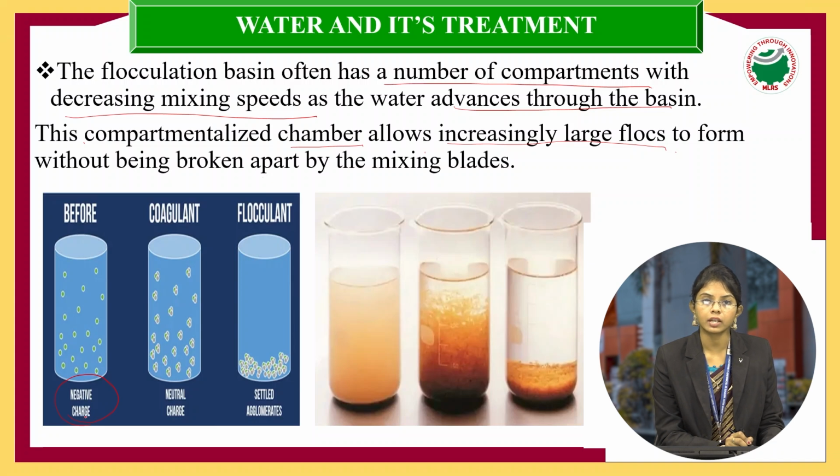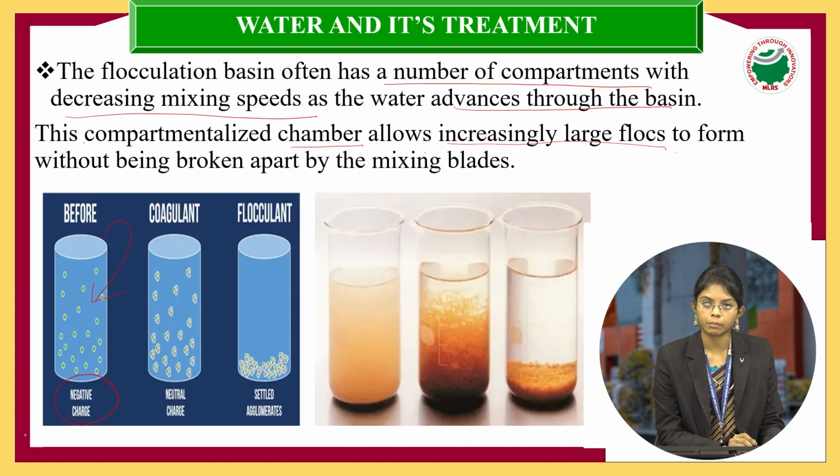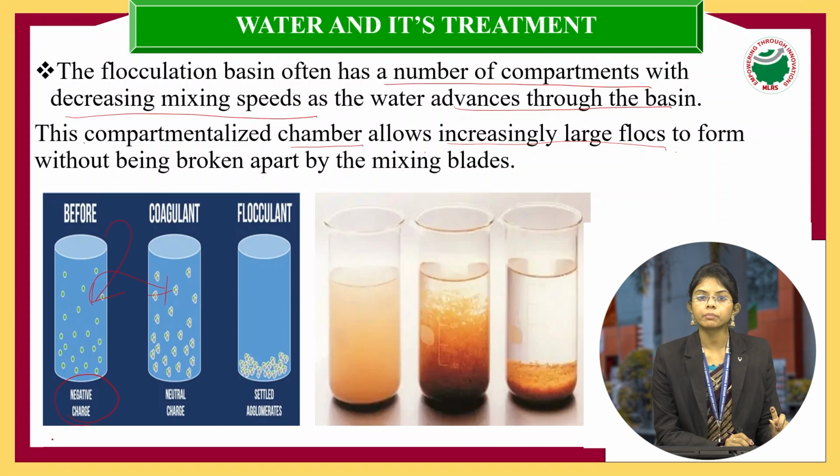Negative charge means fine particles. That means the impurities present in water have a negative charge. So to this negative charge, we are going to add some coagulant, or chemicals which have a positive charge. Now this negative charge and the positive charge will neutralize the fine particles. So if you observe, the coagulant will form smaller flocks first.